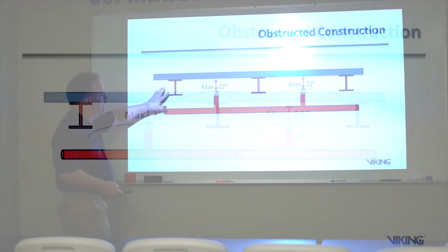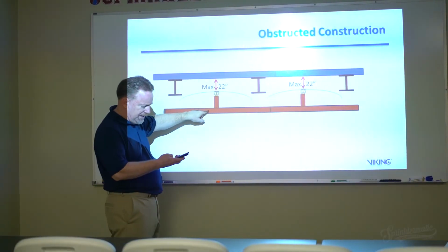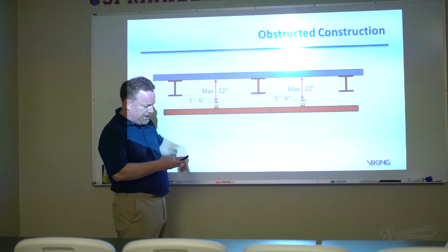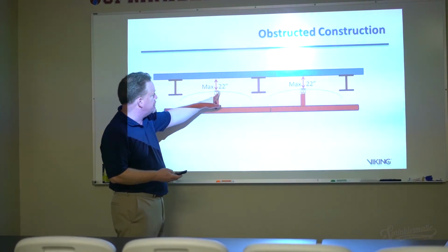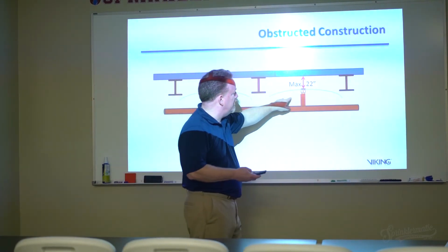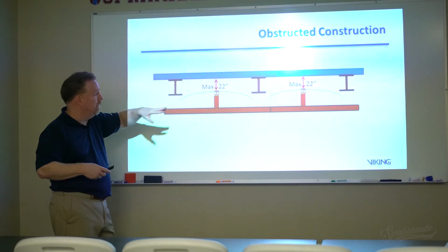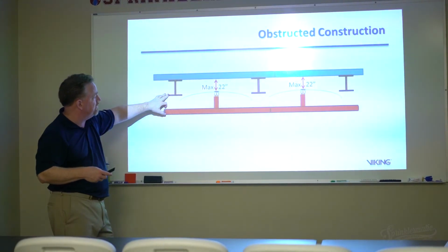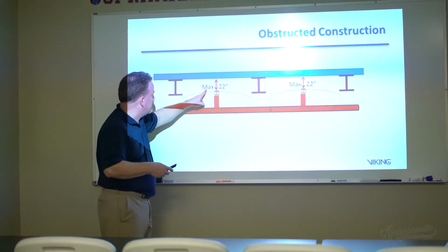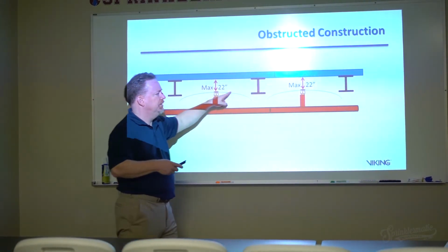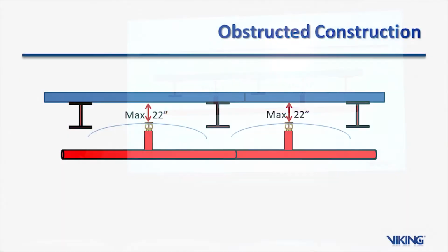Now, that's just if you're going to put sprinklers down below. Now you could put sprinklers up on the same level. That's one of the things that they could have done with that type of construction. One of the things you can do is put your deflector right up at the same level as the bottom of the obstruction.